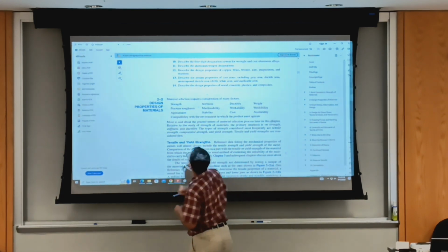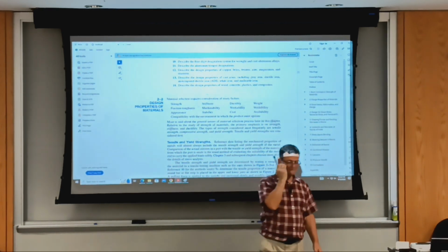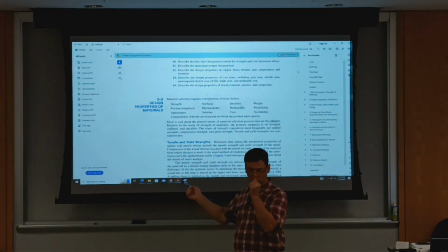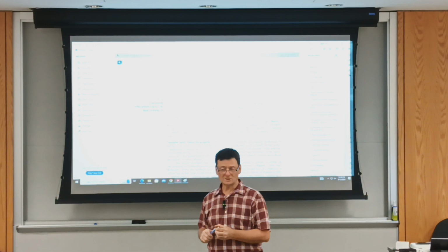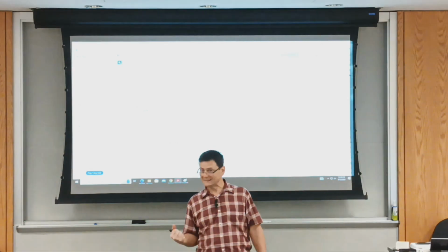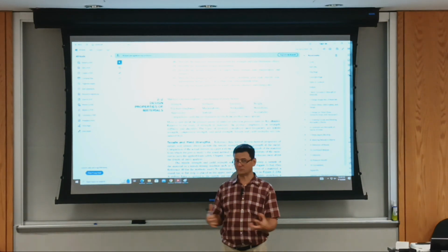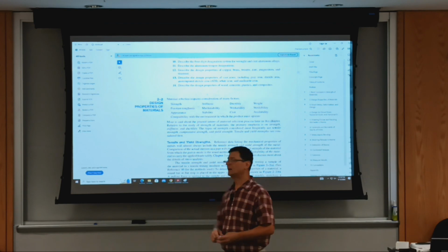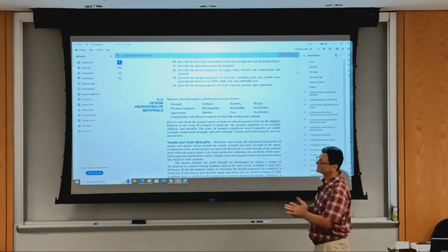And so far, we have strength. We looked at it already. We discussed deflection. That has to do with stiffness. Okay, if you go to the machine shop, you haven't taken manufacturing, but you can introduce yourself to Jack Esparza and ask him to show you a boring bar. Not a makeshift boring bar, one that you buy. And you'll see it's heavy to hold, dense, and it's actually not made of steel, rather it's made of carbide. Why is that? Because carbide is a stiffer material than steel. And aluminum is less stiff than steel. And titanium is stiffer than aluminum, but not as stiff as steel, stuff like that.